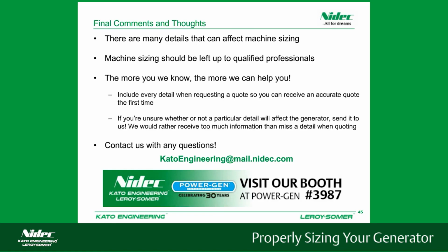Okay, I think we've got time for a couple more questions. So the next question is, how is ambient temperature determined for a TEWAC enclosure? The ambient temperature for a TEWAC is the external air that the generator is sitting in. So if the room that the generator is sitting in is at 40 degrees C, that would be the ambient temperature.